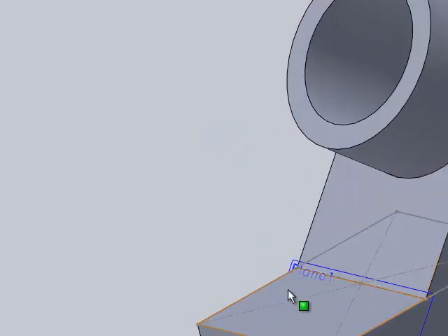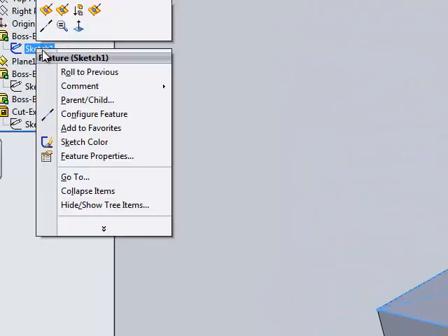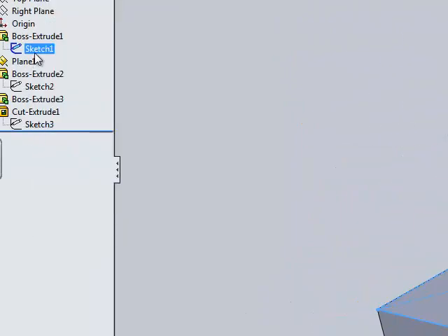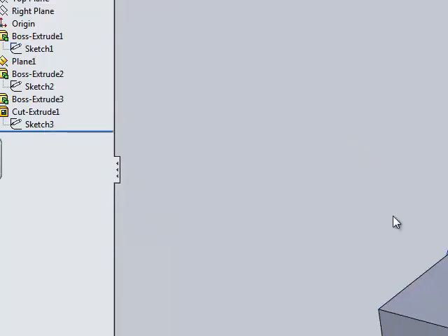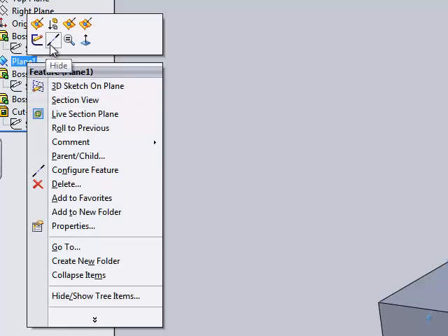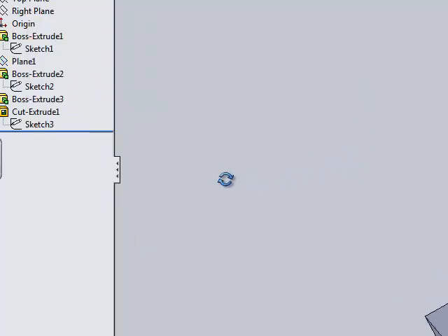I no longer need to see that area, so I'm going to hide this here. Go to Full Preview, and it tells you exactly what it's going to look like. If you're planning on doing these fillets here, you can also hide the plane. The 12 radius will be too big, so you end up with something like this, for this, or anything else.